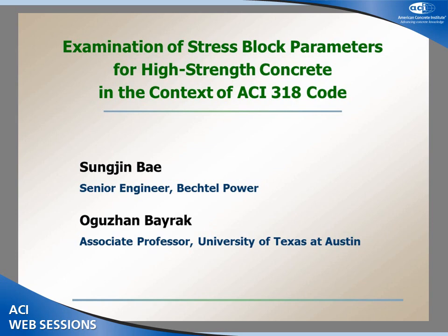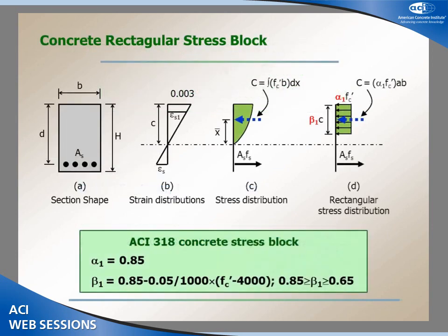First question is, if the ACI 318 expressions potentially have some issues, what are the critical conditions? For example, for which concrete strengths do we have to be careful in using the current ACI 318 expression? And if we want to use other design expressions, among the various design expressions, which one do we have to choose? In addition, if there are code-related strength calculation issues for columns, are there any other similar concrete members which have similar problems? I hope that during my presentation I can answer some of these questions.